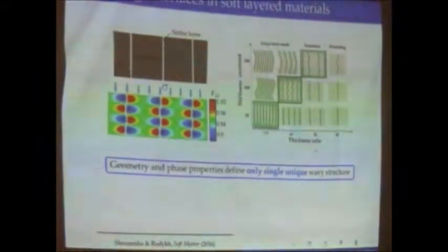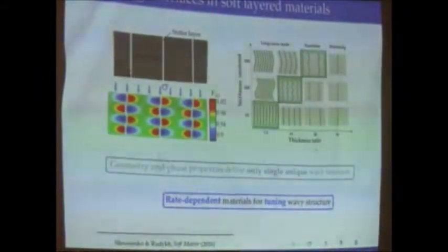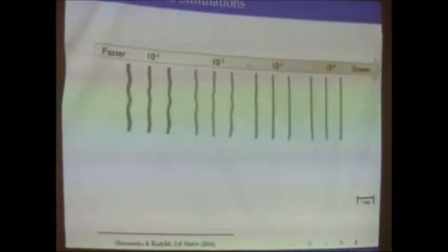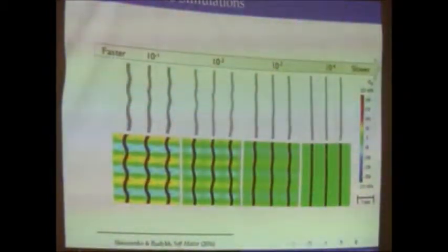start considering inelastic behavior, for example, a rate-dependent behavior. That's what we've done. I'm showing here the experimental results for the same identical material, loaded at different strain rates. This is something that you wouldn't expect: if I load it faster, then at some point, already at the same strain level, I will achieve instabilities, while for very slow loading there is nothing, and we still have a simple type of primary solution without any buckling.